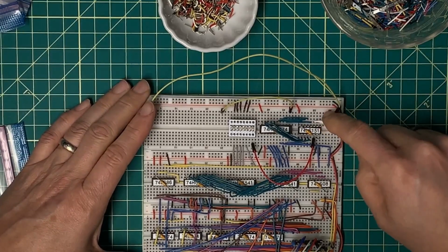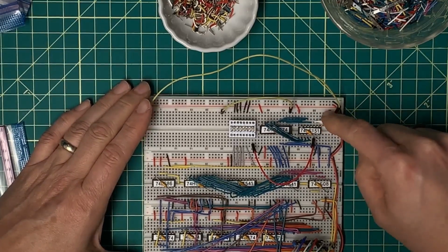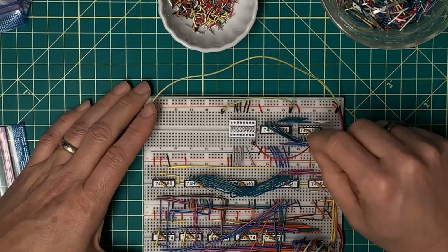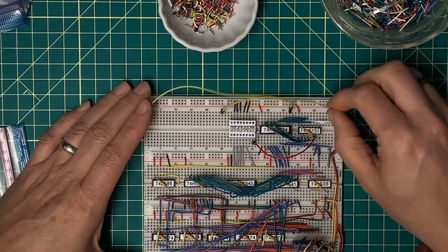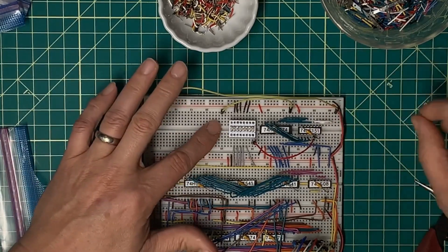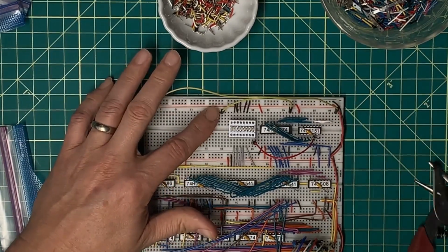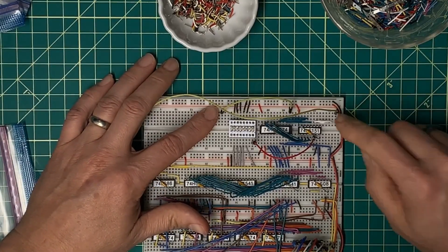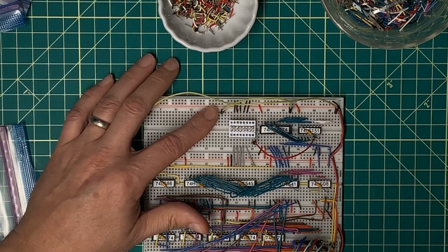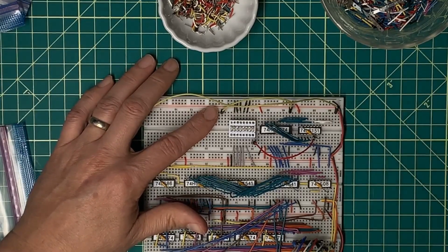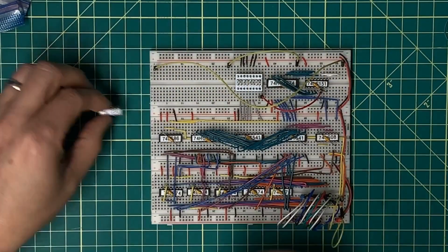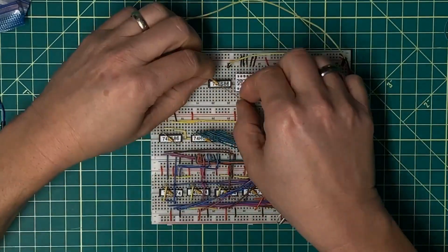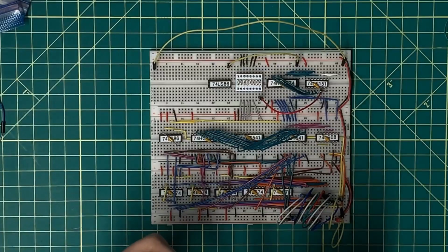So now I have to create a 4-pin ribbon cable for taking this signal from the control module. My output has to be exclusively ORed with this signal, and I'm going to have to do that on this side of the board. And then I'm going to have to pull clock in from the control module as well. I'm wondering if it doesn't make sense to include clock in this bundle. I don't have the board in front of me. I'll have to look. Finally, here's the exclusive OR that I'm going to use to condition that signal, whether or not it's supposed to be inverted or not.